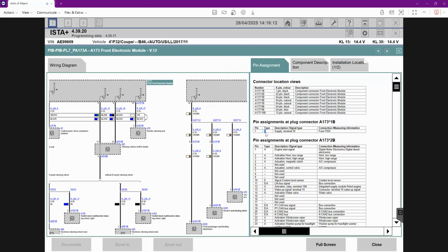See, E means input, and A in the German designation on the pin connectors means output. See, E means input and A means output. So that's what they mean by that. And as you can see, this one shows start signal. You see the A is an output from the BDC from the CAS side, to turn on terminal 50, to make the starter turn over, to perform engine start. As you can see the type of the pin. You understand me now? It shows you the purpose. You understand the type of the pin assignment. E means input and A means output. That's what the Germans assign.